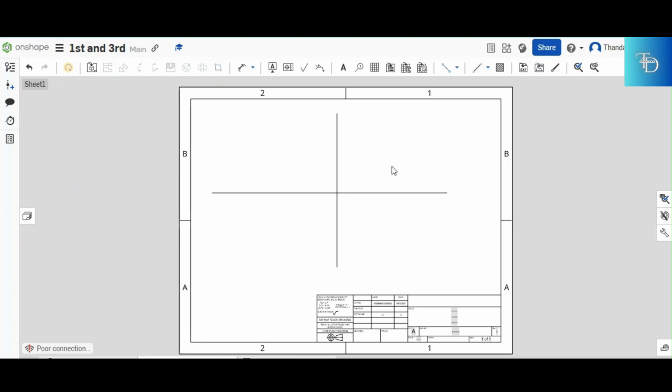All right, now for the third angle orthographic projection, it's another story. But still you have your horizontal plane, and then the positioning of the views differs because the third angle represents the right view. It comes with the right view. It gets the top, the front, and then the side. It's a right view. It's no longer the left view now.